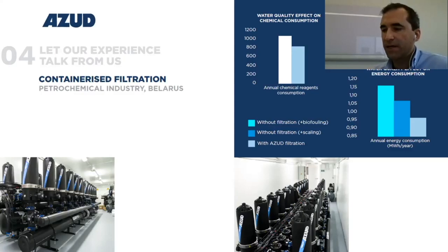So, as a conclusion, you can say that a correct water filtration design can eliminate these risks by removing the suspended solids present in the cooling water circuit, and self-cleaning disc filtration technology can provide a cost-effective solution, contributing to a greener environment and to a circular economy.